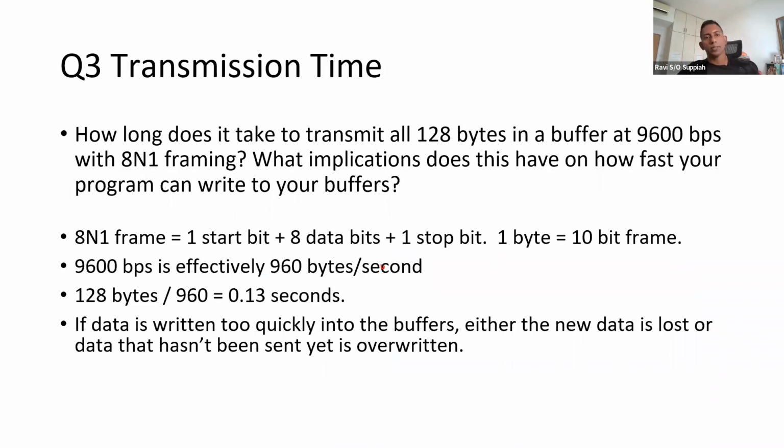In this question, we are looking at transmission time. We are asking how long does it take to transmit all 128 bytes in a buffer at 9,600 bps with 8N1 framing, and what implications does it have on how fast a program can write to the buffers?